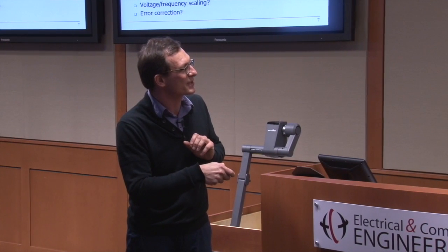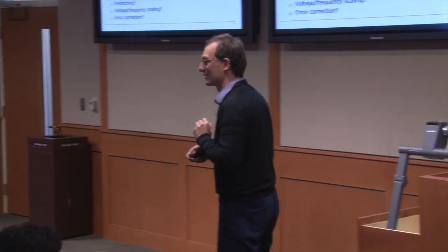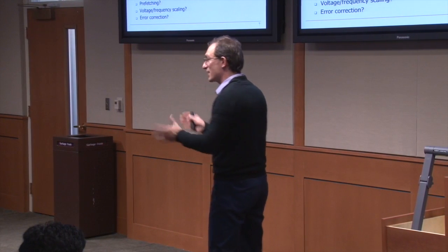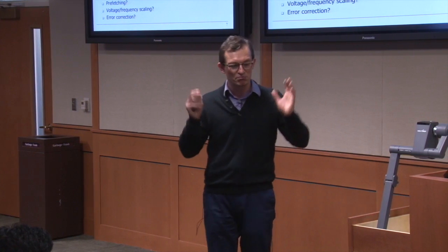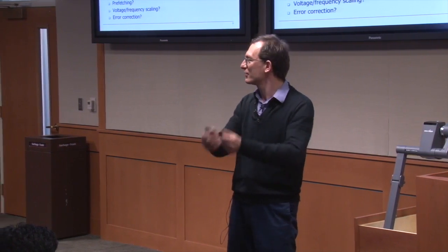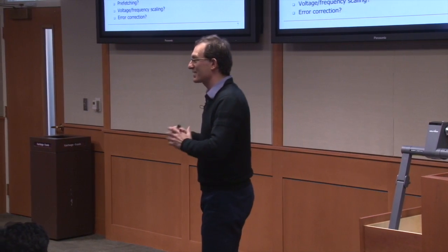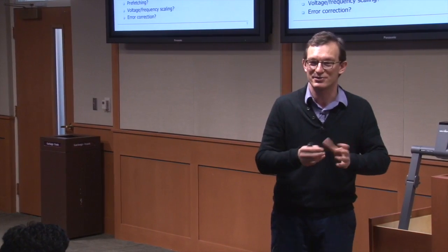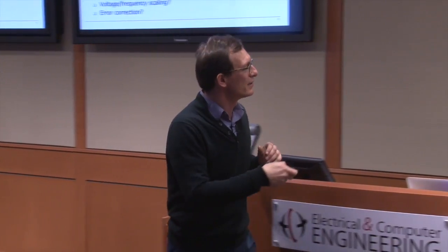OK, there's voltage frequency scaling. That is actually exposed to programmers, right? System software programmer needs to do that. But that doesn't have to be. Microarchitecture can do it on its own, right? The hardware can say, oh, this core is right now idle, so I'm going to reduce the frequency of it, right? Or mostly idle, so I'm going to reduce the frequency of it. That's an example of voltage and frequency scaling not being exposed to the programmer. There are no instructions that can change your voltage and frequency, but the hardware does it automatically.